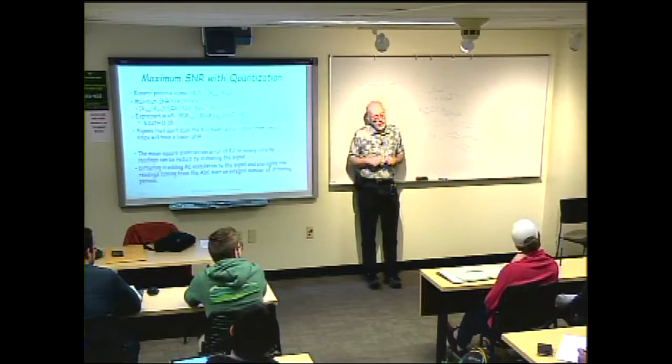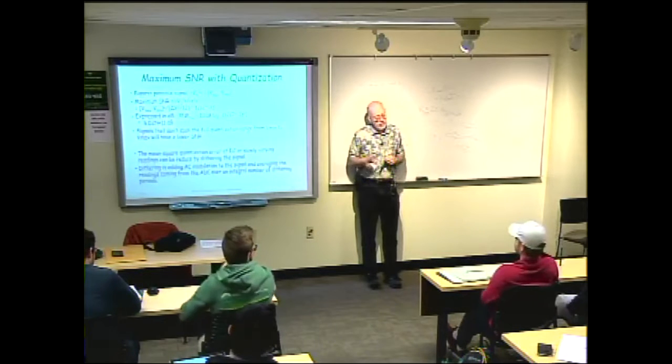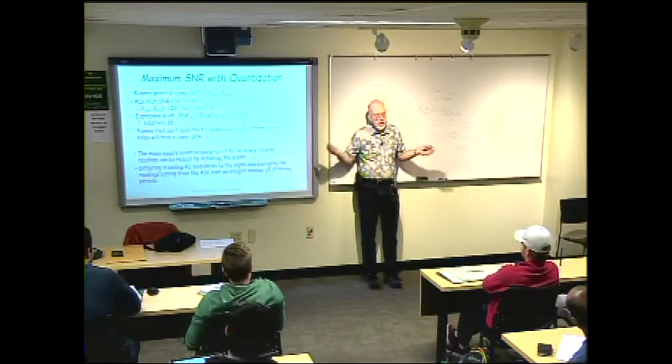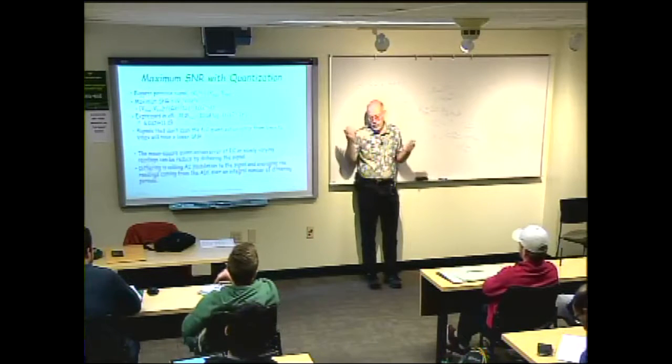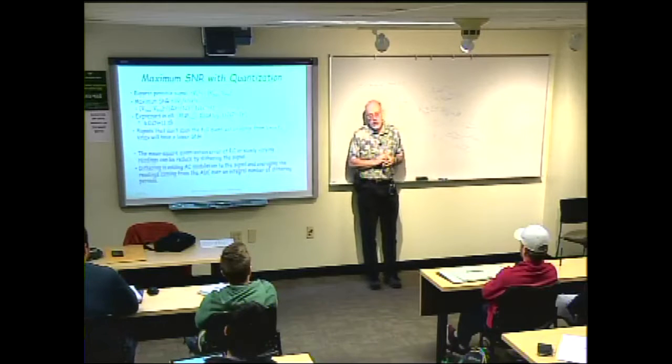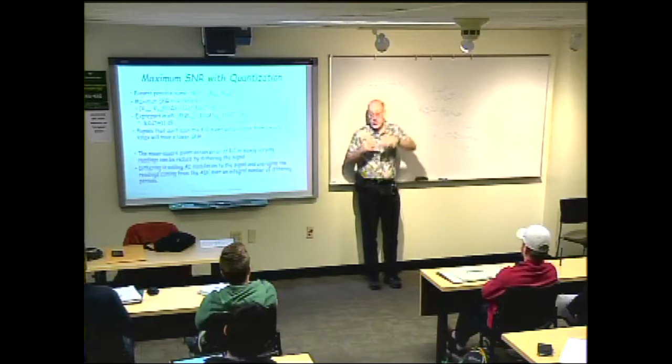Sorry, I'm taking side turns and coming back here. So on a scope like that, does it matter if you're trying to make the signal big or not? Turns out the answer is yeah, it does. Because those are 8-bit scopes. They quantize the display into 8 bits. But it's the display size that determines the range of the A to D converter.